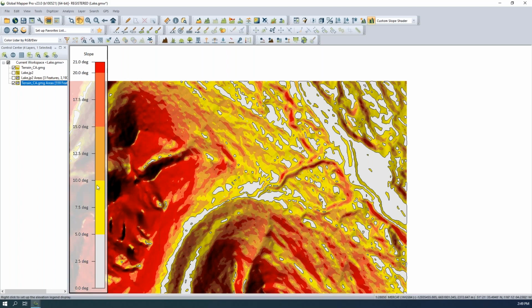So this is a great tool for any raster layer that you have in Global Mapper. You can create vector features in a more automated way rather than having to manually digitize around a lake or somehow crop the terrain grid here by slope in order to extract some features. So really working to improve efficiency with the workflow and just some more data creation here.